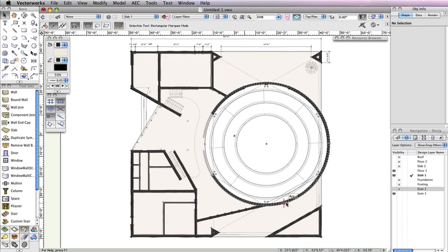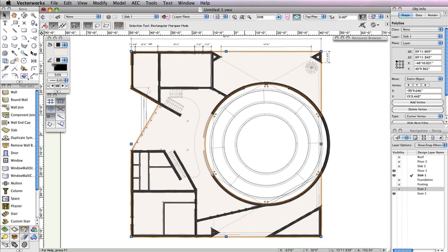Now we need to clip a few more extraneous areas before we can complete the polygon that will be used for the slab. This time, we'll use the Clip tool as a different approach to clipping objects. To begin, select the polygon. Then select the Clip tool from the Basic Tool palette. Also in the toolbar, enable the first mode, Exclusion mode, and the fifth mode, Polygon mode.